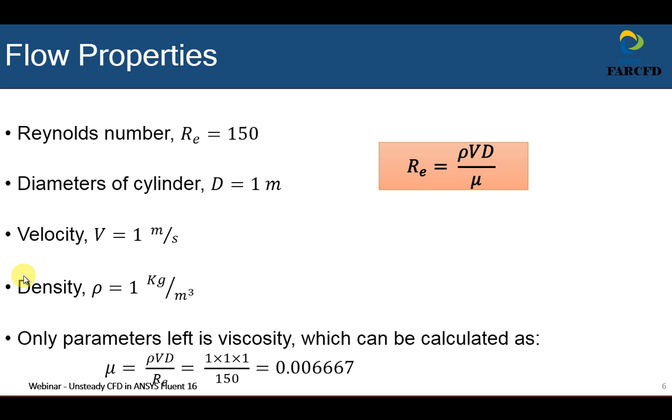once you match the Reynolds number, you are able to get the same flow behavior and flow parameters as done by someone else. We can choose any value of variables in Reynolds number and still get the same results if the combination of these parameters does not alter its value. It is one of the advantages of CFD compared to experimental methods that we do not have any limitation of size, material properties, and flow conditions. For example, we can use very high temperature in CFD, but it is not possible to do it in a laboratory.